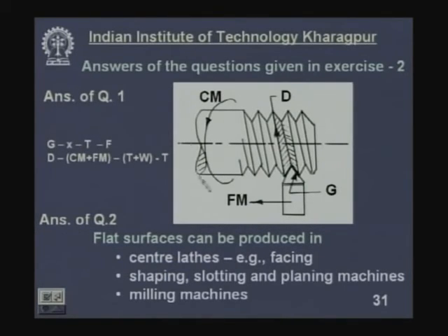This is thread cutting. So, the job is rotated, cutting motion, this is the feed motion. Now, this is the generatrix and this is the directrix. So, this combination of directrix and generatrix produces this surface, these helical grooves. For this helical groove, the generatrix is connected with the form of the tool, no motion, but it is a part of the tool and the form of the tool.